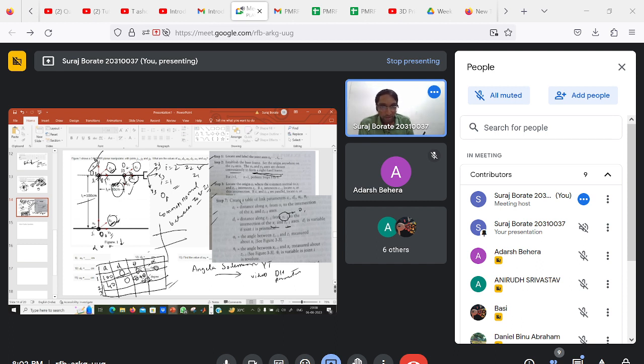There is a 90-degree offset by labeling the axis, and then there is the joint angle. Already x1 and x2 are at 90 degrees. Earlier, x0 and x1 were aligned, and then the rotation of the joint was causing theta, so it was theta 1 plus 0. Here it is 90 plus theta. So initial position 90-degree offset, and then whatever the link rotates.